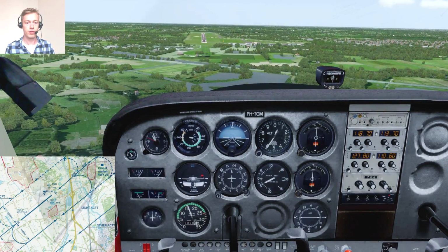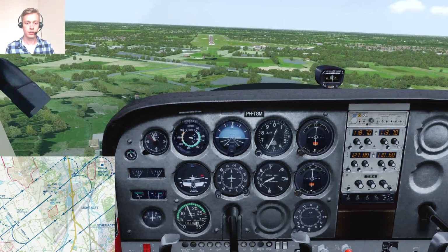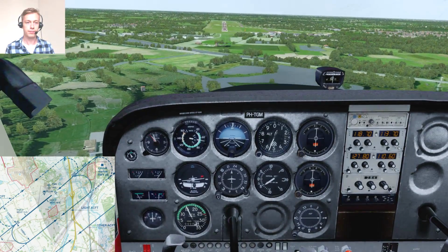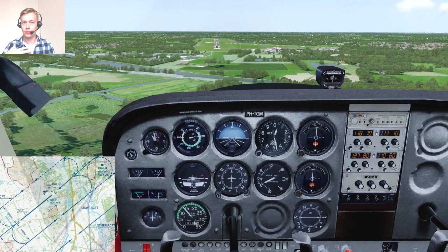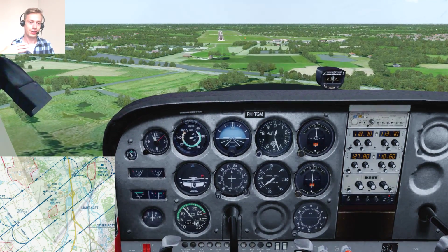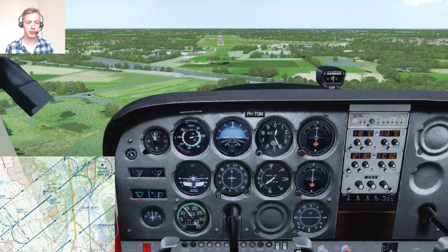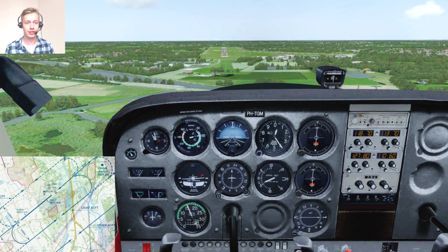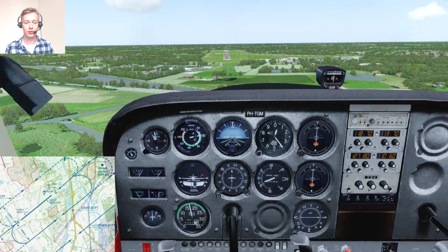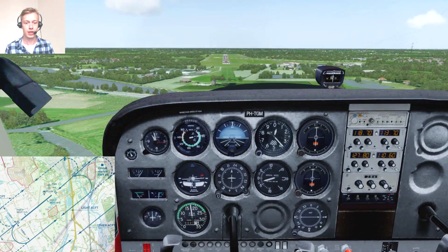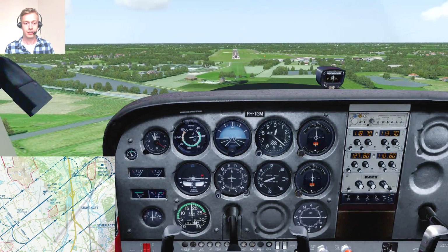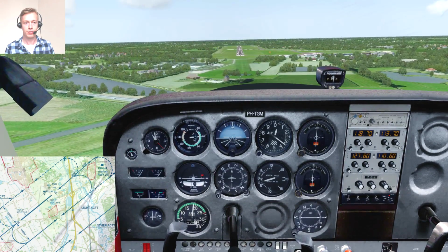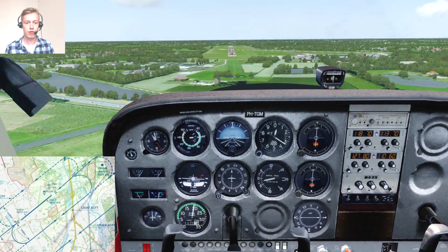Again, there may be traffic in front, so keep that in mind. I'll put out some more flaps this time, so we can fly nice and slowly. As you can see, also for me, this is practice. This was the first time I flew a circuit, so it's nice to keep practicing this and take it easy. Getting used to navigating using visual landmarks, getting used to flying a general aviation airplane. Gives also time to trim the aircraft a little bit. Keep the power up if necessary.